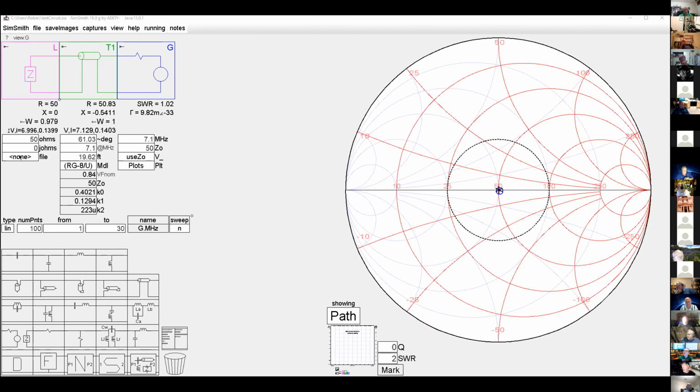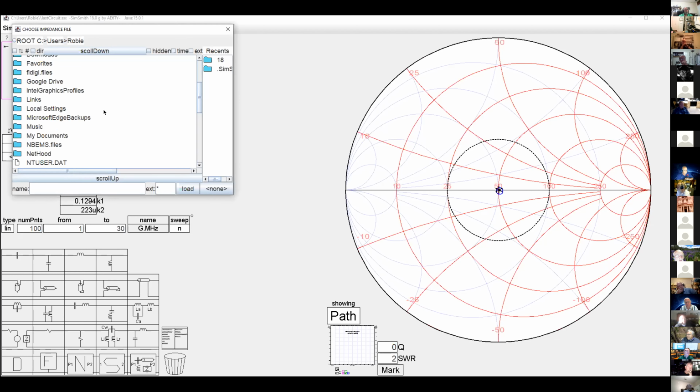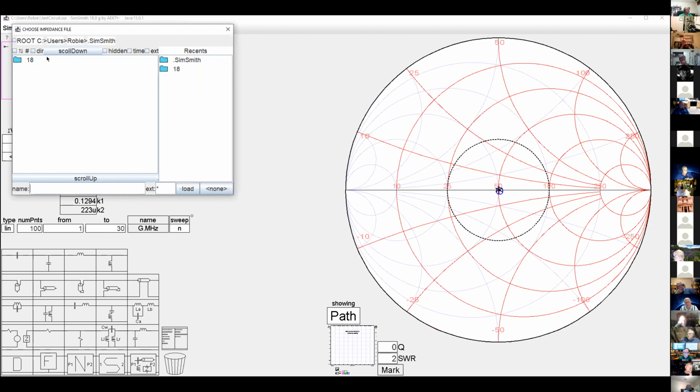Right. So if you notice right here where my cursor is, where it says none, I have no file loaded in for the antenna. Touchstone files are available. I don't have it pointed to the right location here, but I can import touchstone files. I can import text files out of EasyNet. When you take EasyNet and put in an antenna physically, and then run the far field analysis and the SWR analysis, you specify certain frequencies. A file is generated by EasyNet that contains the frequency versus impedance of various points that it uses to calculate the SWR. That information can be imported into here.